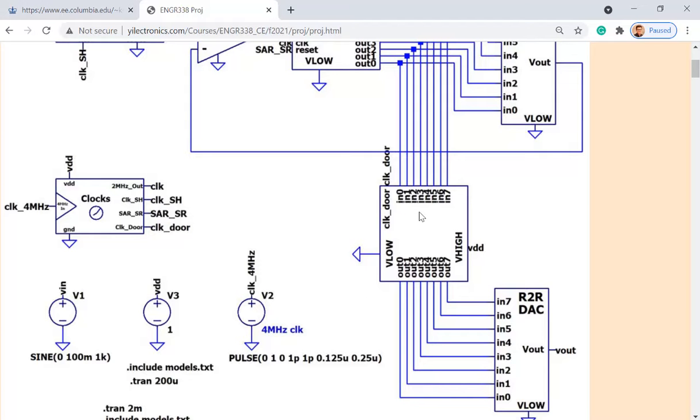So when are you going to use a parallel in, serial out, and why? They're all digital. This looks like parallel in, serial out, but it's not serial. It's digital in, analog out. When I'm talking about parallel in, serial out, it's all digital: parallel digital in, and serial digital out.